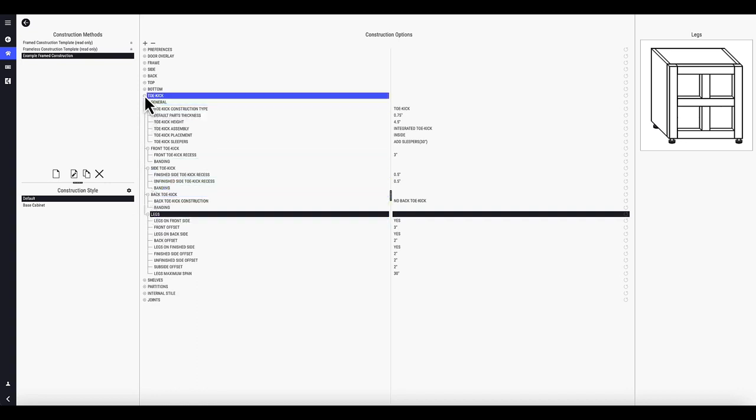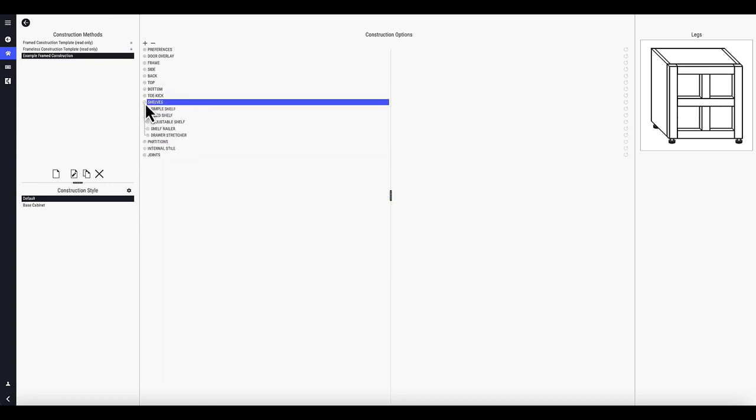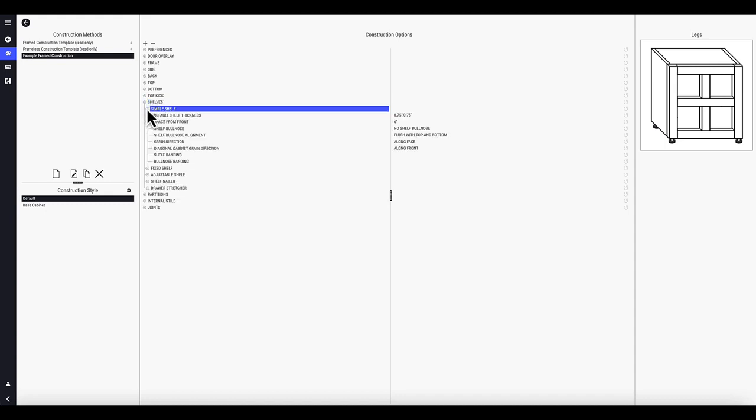There are 3 general shelf element types in CABuilder: simple, shelf, and adjustable. The first of these is the simple shelf. Simple shelves are general shelf elements that one uses to hold objects within a cabinet. It can be made up of 3 sub-elements: nailer, shelf board, and bullnose, the latter 2 being guided by the simple shelf settings.